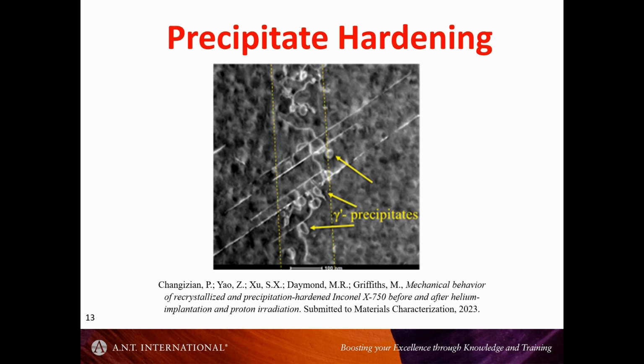Dual phase alloys, niobium dual phase alloys, they do tend to be harder still, stronger, not necessarily stronger and harder, so a little bit less ductile than zircaloys, but a lot of that essentially comes from the grain refinement. So the dual phase nature in a zirconium alloy, for instance, allows for smaller grains. Allows one to retain smaller grains in the as fabricated product. And a lot of the increase in the strength comes from the effect of the second phase on refinement.